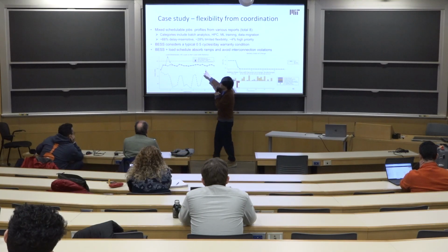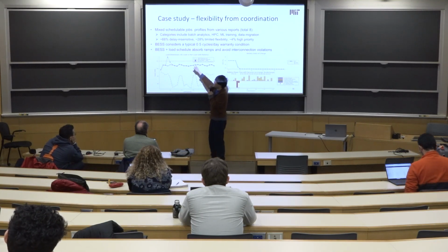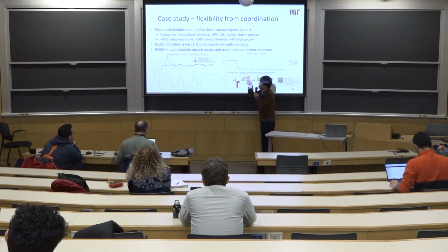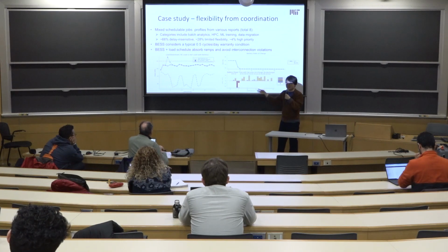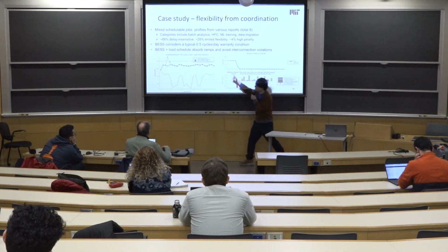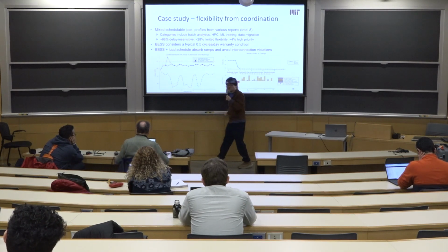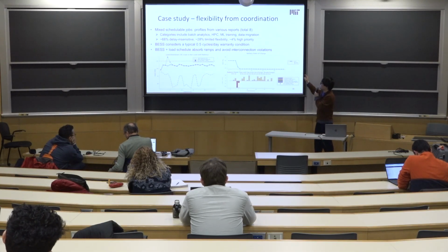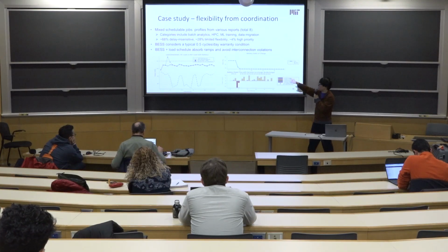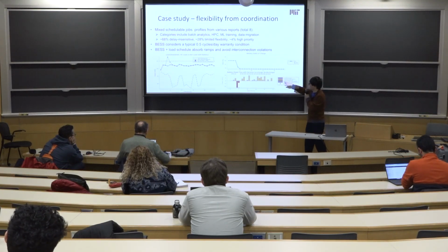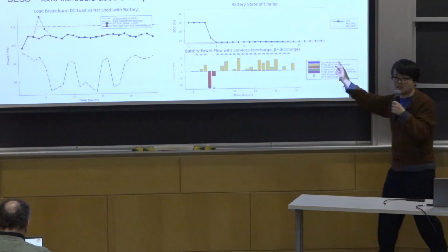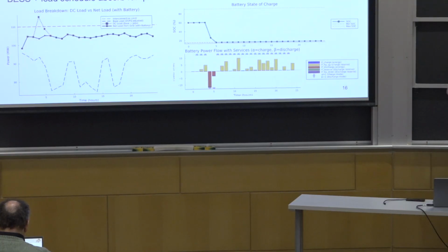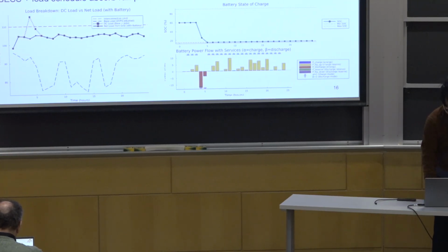The peak demands are managed by these smart schedulings as well as the additional battery buffers, and those ramps are also controlled. So all the constraints are satisfied. The battery operation is basically discharge to control the peak ramps and also providing additional capacity as an ancillary service.